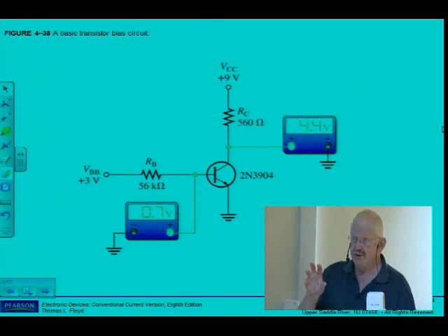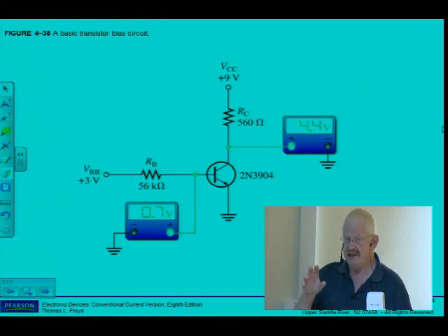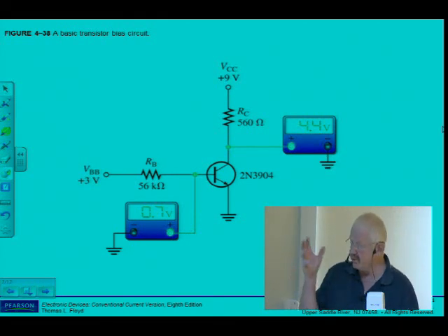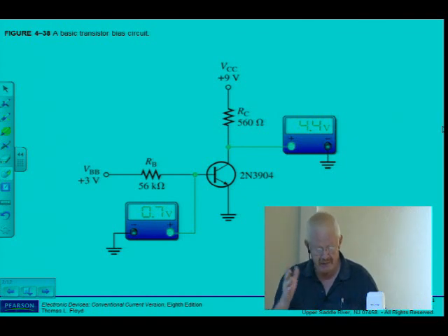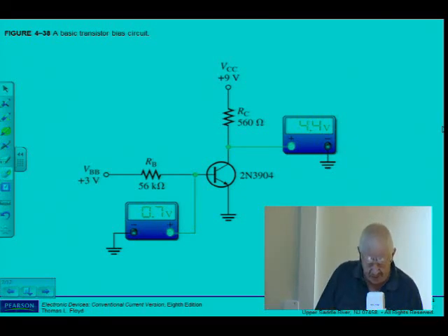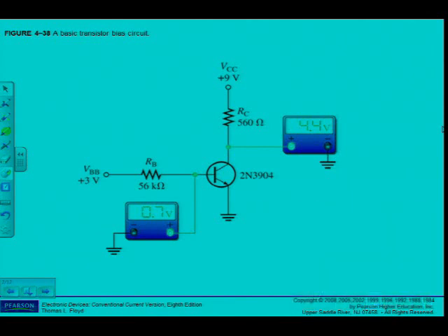So what you have to do for your calculations, analytical analysis or fault finding, to be able to determine values more or less in the vicinity, is take the midpoint or the average of the minimum and maximum values. It will be for beta DC, in this case 200, for the 2N3904.